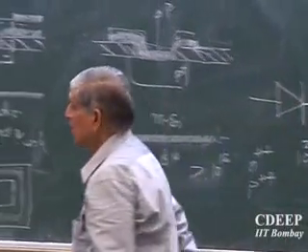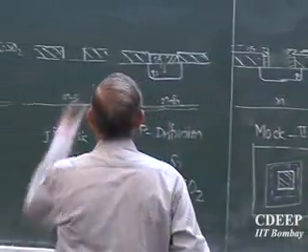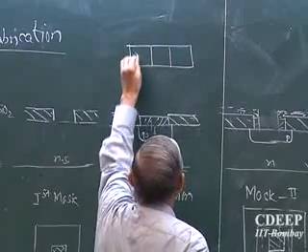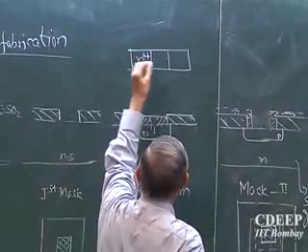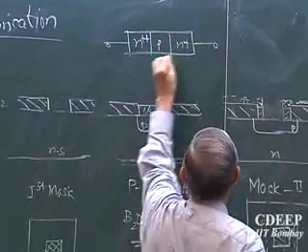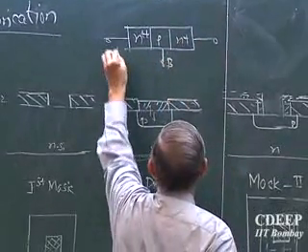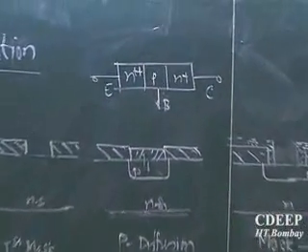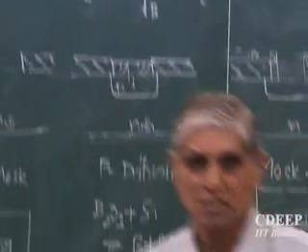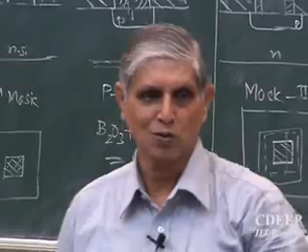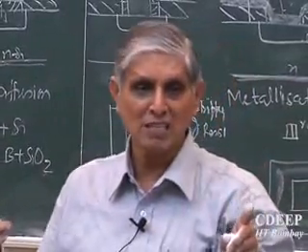In case of a transistor, if you look at NPN transistors, this is the heavily doped region. This is your base, this is your emitter, this is your collector. So emitter and collector are differently doped, though both are N. Is that correct? One is plus plus, a heavily doped emitter. Therefore it is not the same as the collector.